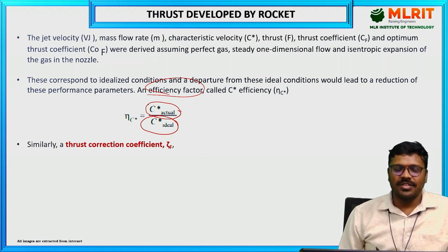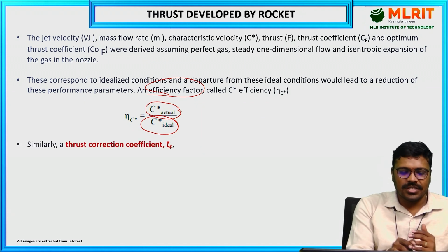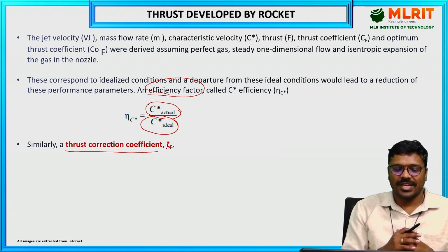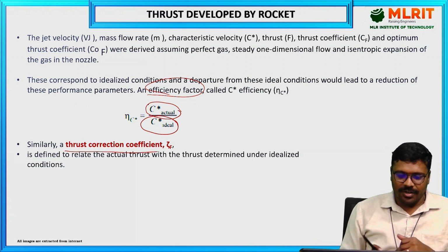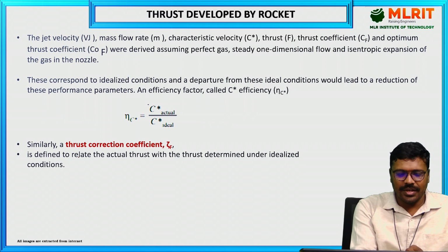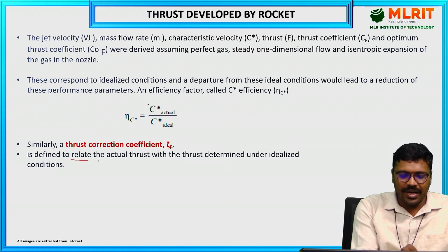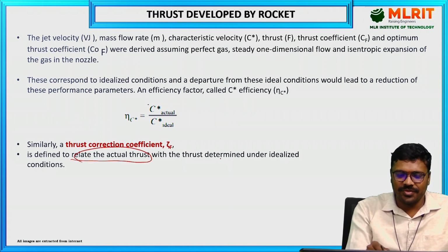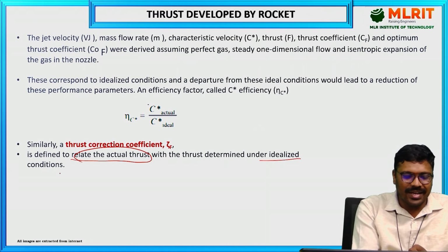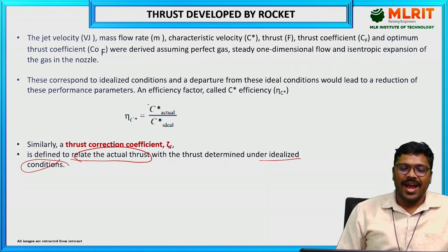And next there is one more factor, the thrust correction coefficient. It is defined to relate the actual thrust with respect to the thrust developed under ideal conditions.